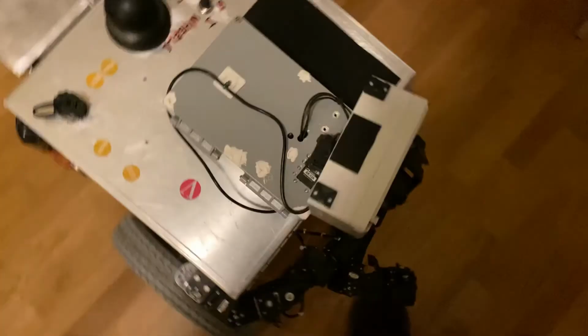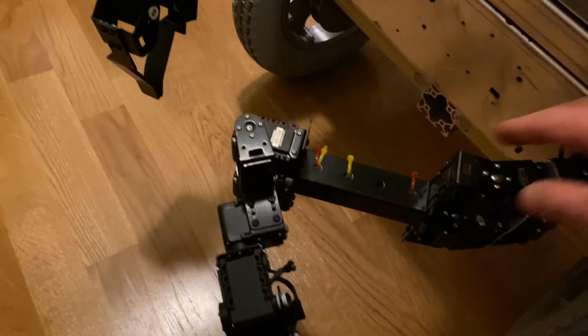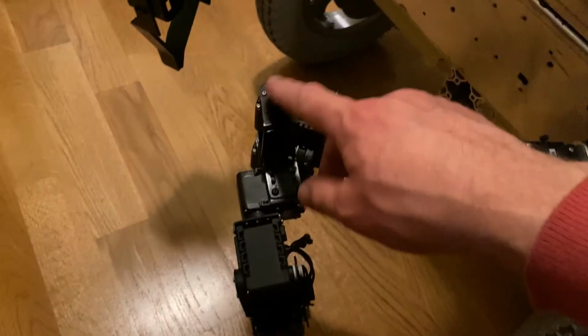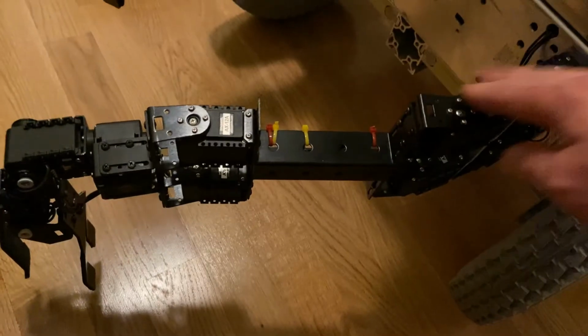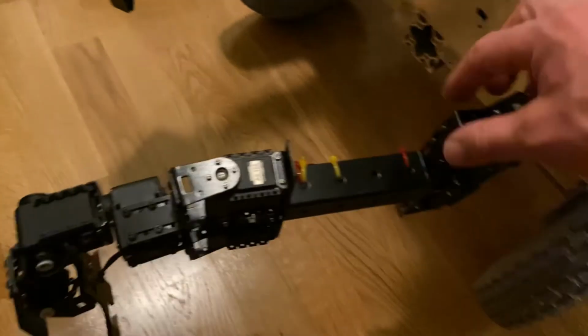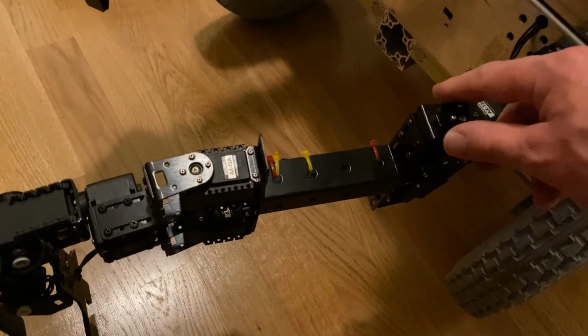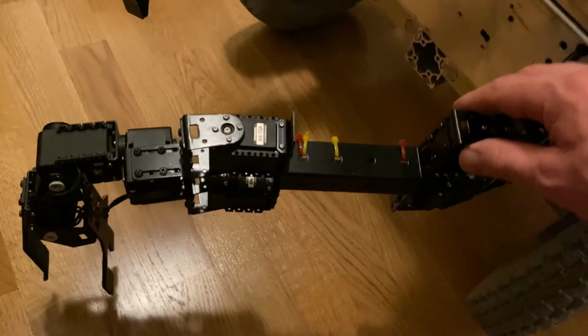I also changed some things in the arms. This upper arm was working fine, as I always planned it. This one had problems in some of the actuators. Now it's working more horizontally, not touching the ground. Sometimes when it touched the ground, I don't know what happened, but one of the actuators got a kind of impact and always overloaded, shut itself down and became lame. So I did a bit of modification to the structure of this arm.